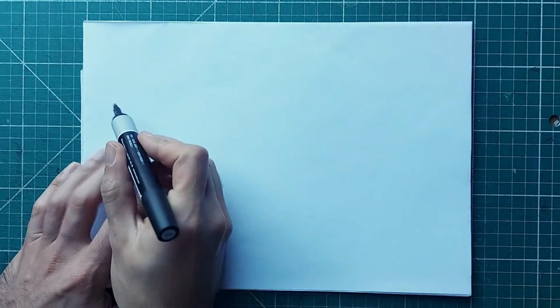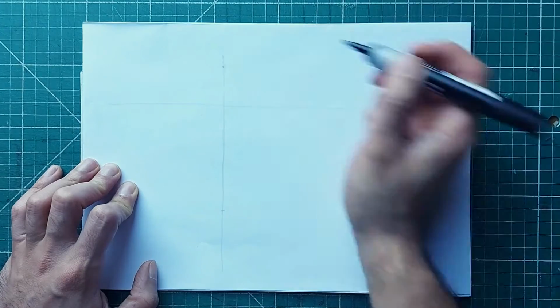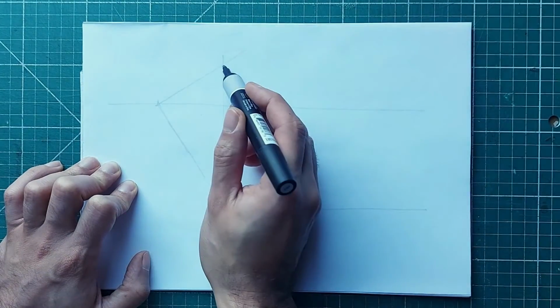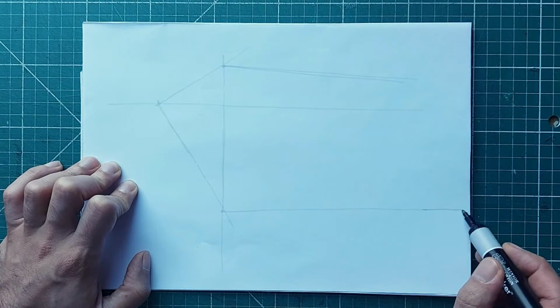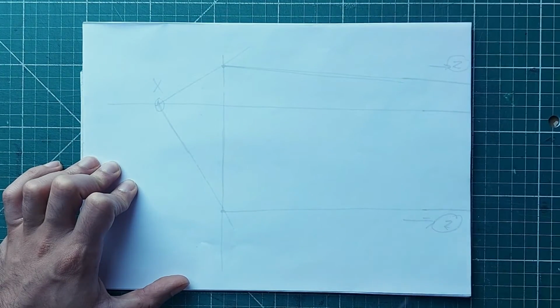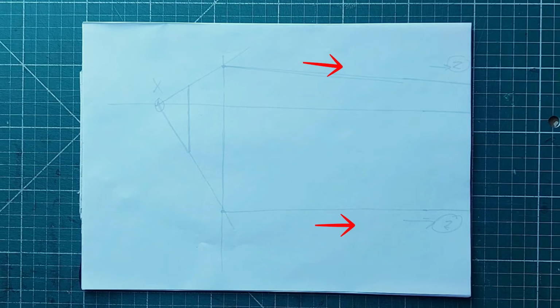The final thing to cover here, then, is a way to help you more accurately work with vanishing points located off the edge of your paper. Scott Robertson calls this the Brewer method because he learned it from a guy called Brewer, so we'll credit him here too. It's very simple. Let's say we have a box and we draw the nearest 2 faces in 2-point perspective. The lines only converge a little, so the vanishing point is off the paper. Because there is some convergence and the lines are getting a little closer as they go, this method will work.